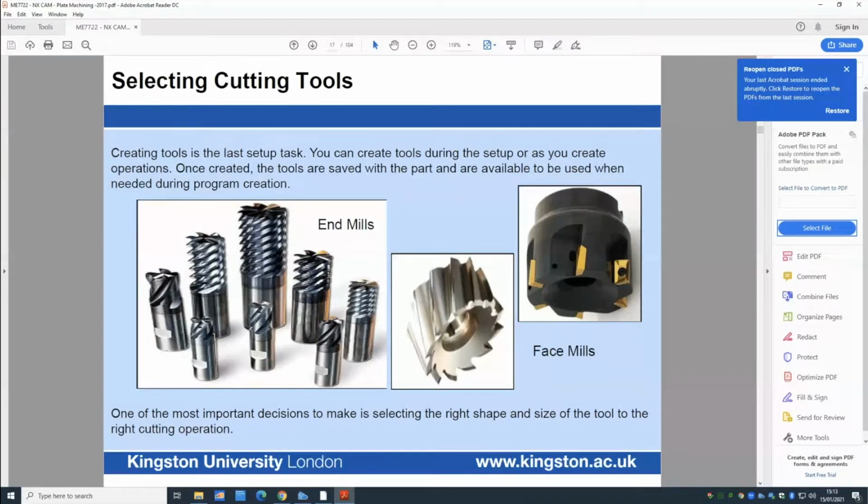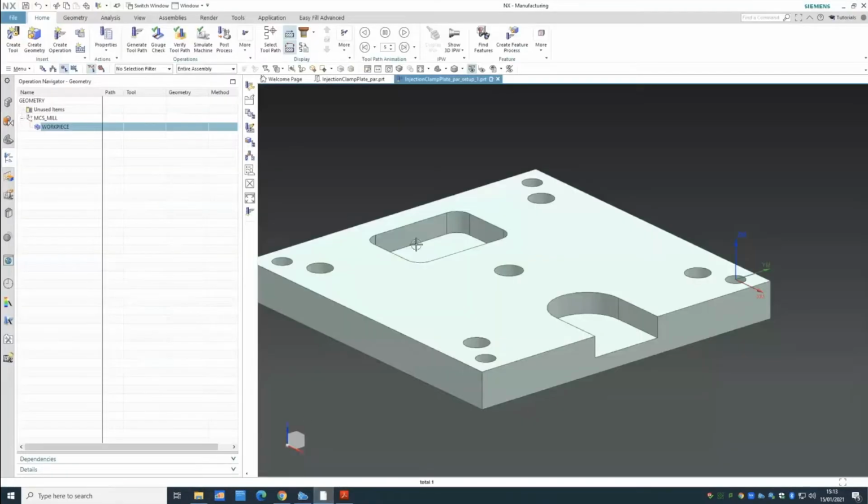So let's say you're gonna operate on here. If you want to do it by hand, you have to first take the part, look at it to see where you want to start. This is what you've done. You've defined the coordination system. Then you want to see how much pressure you want to do, for instance, if you want to do these drillings on the drill. Then you need to put the correct drilling size into the drill to be able to do it. So you have to define the tool.